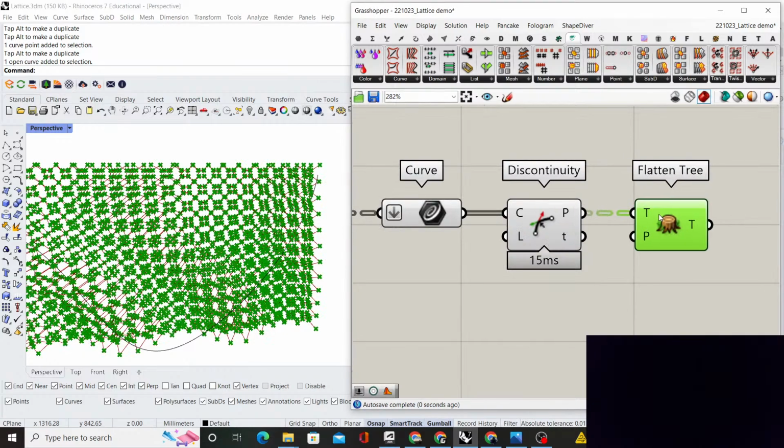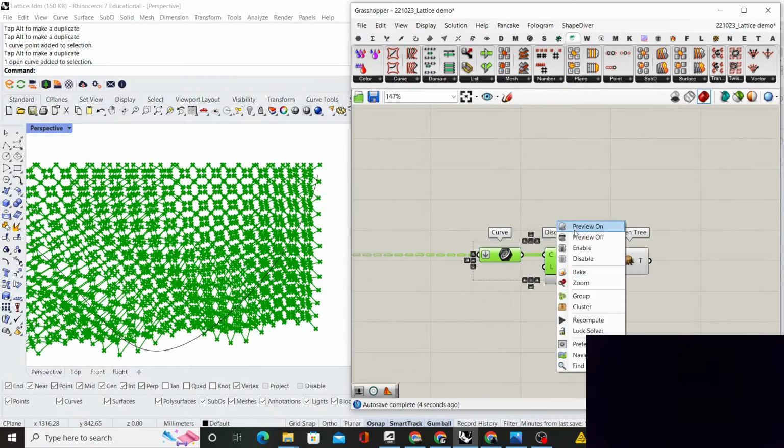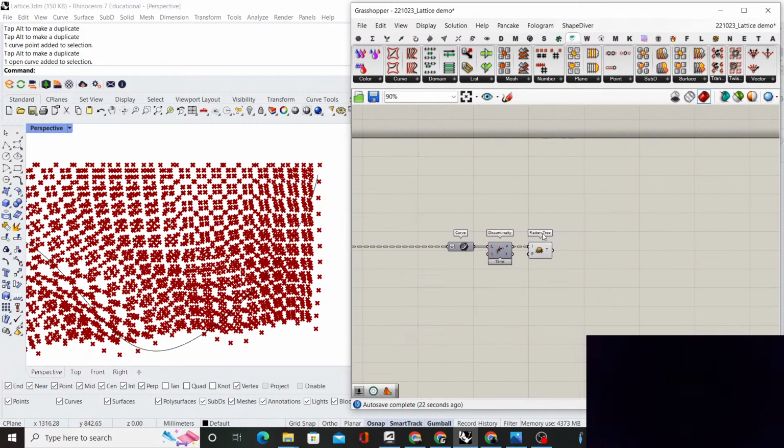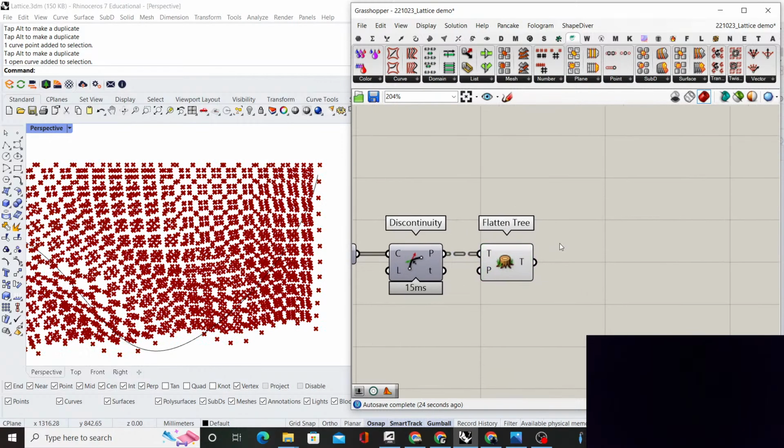It's better to almost never flatten anything in your Grasshopper scripts, but right now, for the sake of time and simplicity, we're just going to do it because we're dealing with only one wall. If we dealt with multiple walls, we would have to use shift paths instead to make sure that we deal with each wall, not all of them together, because it's going to mess up our workflow. But now we can afford this, so let's flatten the tree.